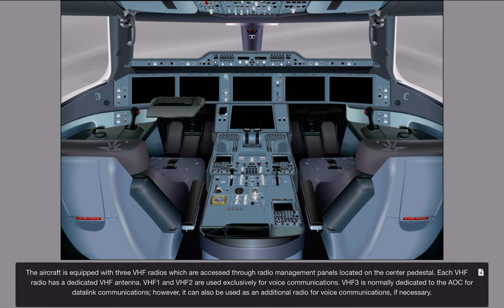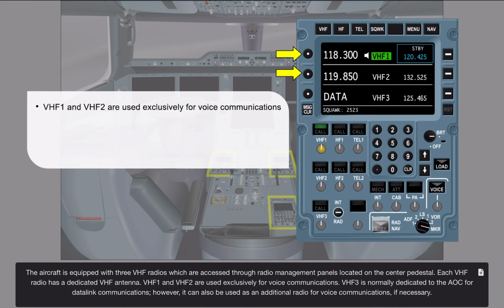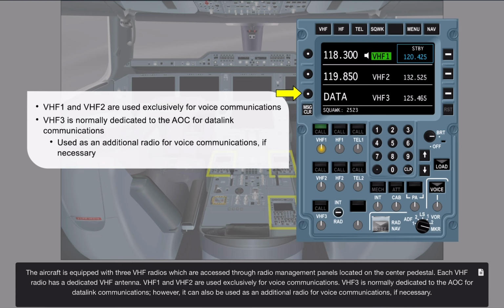The aircraft is equipped with 3 VHF radios, which are accessed through radio management panels located on the center pedestal. Each VHF radio has a dedicated VHF antenna. VHF 1 and VHF 2 are used exclusively for voice communications. VHF 3 is normally dedicated to the Airline Operational Control for data link communications. However, it can also be used as an additional radio for voice communications if necessary.